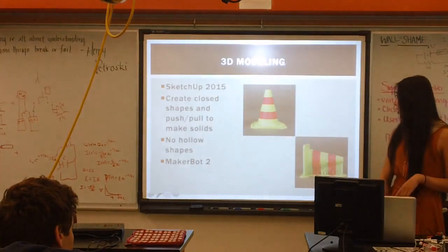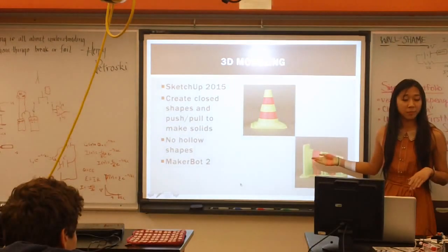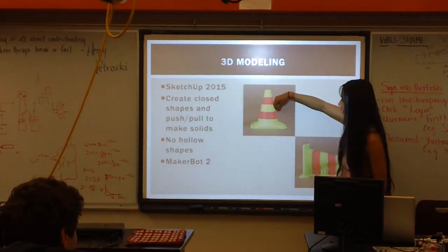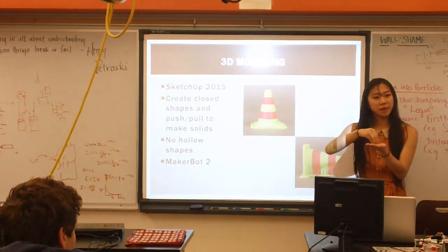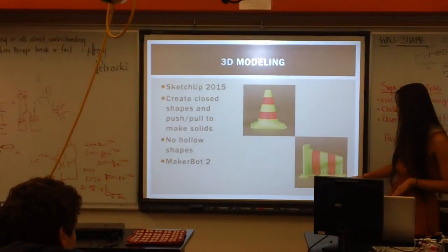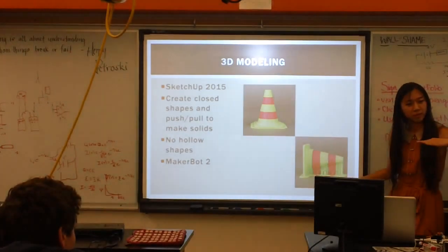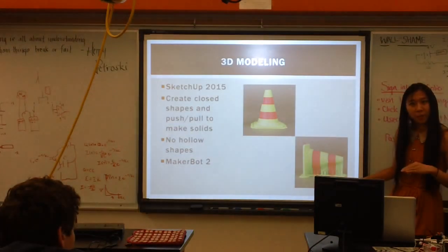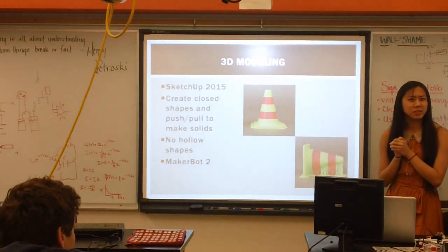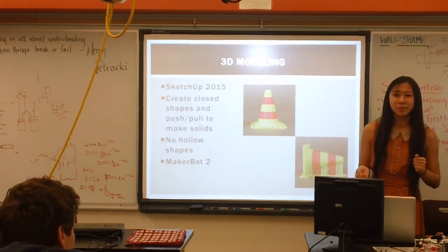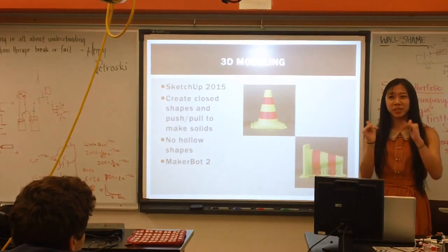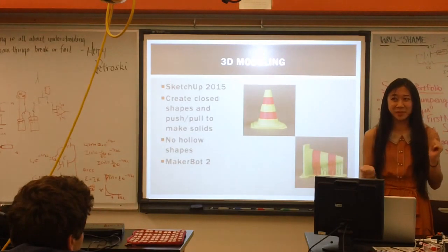And so, what I have here, I've shown two things that were printed using the MakerBot. This thing was just printed from the bottom up. And so the printer was able to print every next cut of the object on top of another piece of the object. But in this version, this cone was printed sideways. And so the person actually had to build all of these fillers and chop it off afterwards, because these are supports for the plastic pen to print on top of. Does that make sense? This is really important to note, because if you end up printing something and we haven't planned it through properly and you're trying to print on top of empty space, your thing is going to look really deformed and sad, and it's going to be a waste. So don't do that.